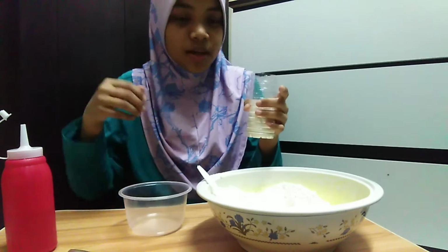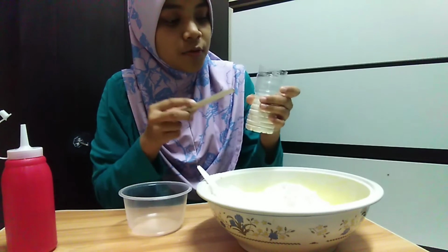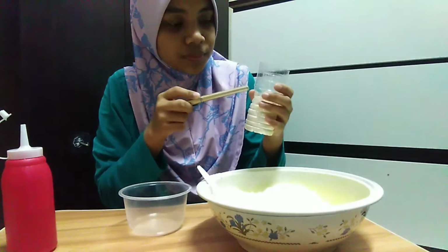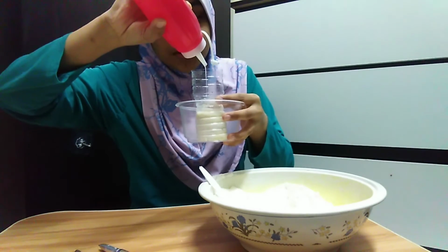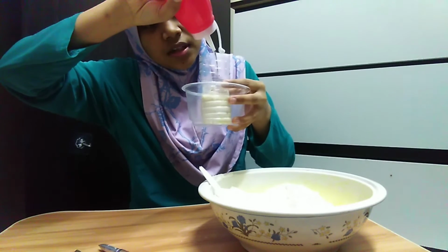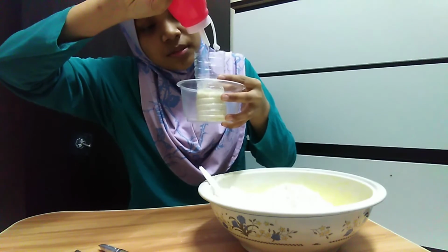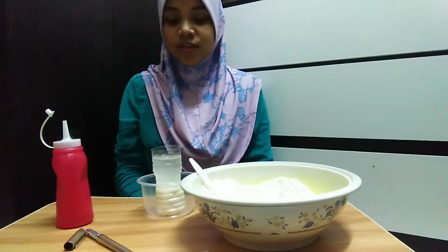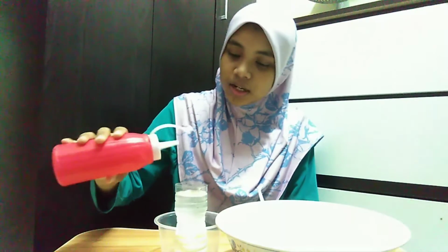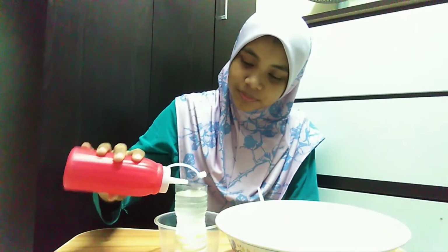After that, we make 4 water level marks above the soil compaction. We put water until the bottle is full and reaches the highest mark inside the bottle. We leave it for a while so that the soil sample can be fully saturated. Again, we add water until it reaches the highest mark.